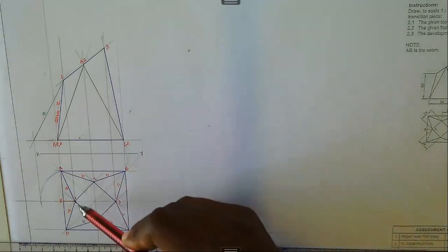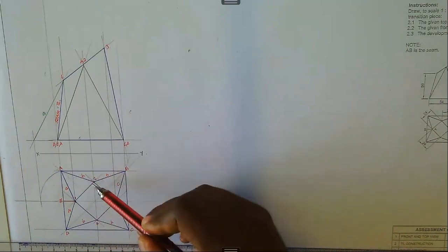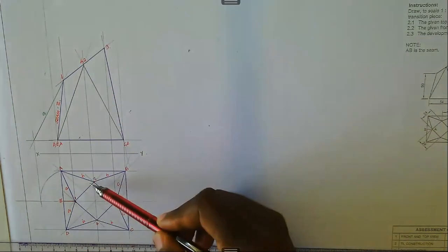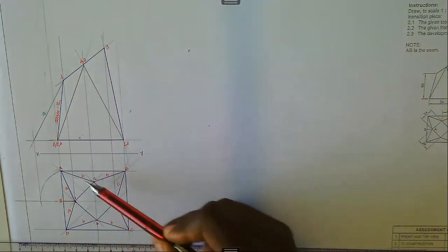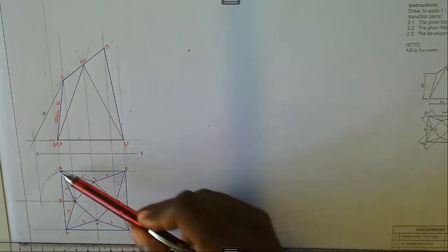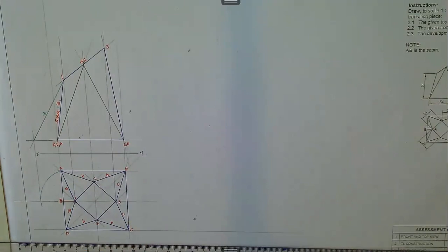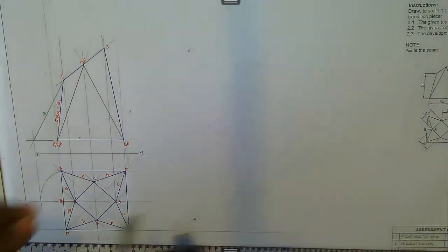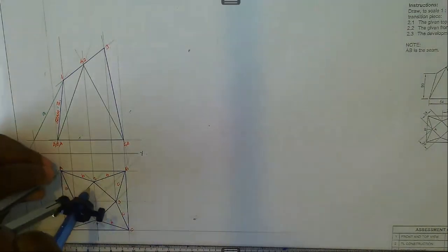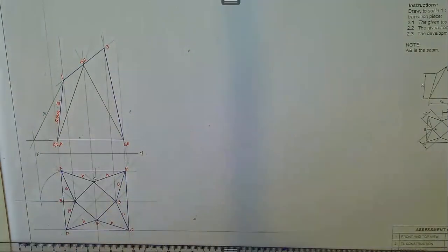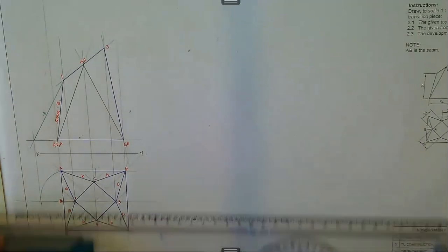Right, then the next one that I require is line B. I need the true length of B. I can swing like that, standing at point A. Stand here, then swing. So what I'm going to move is point number 2, which I'm going to extend like this.